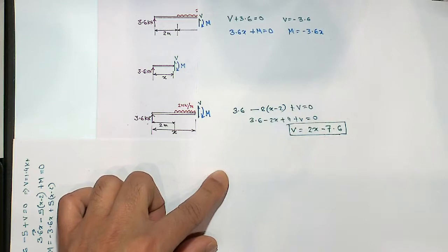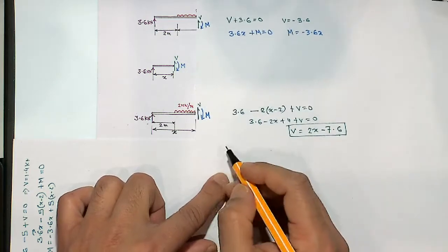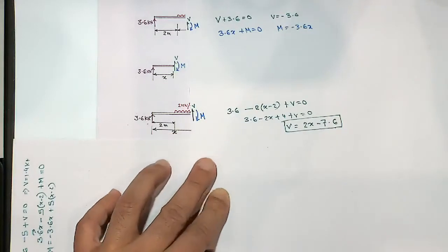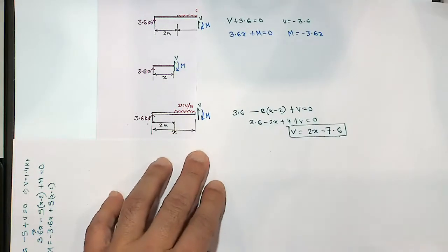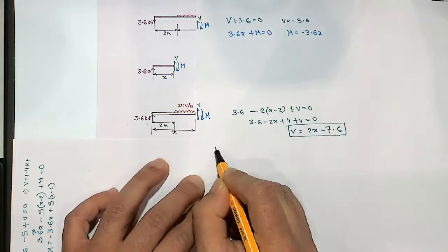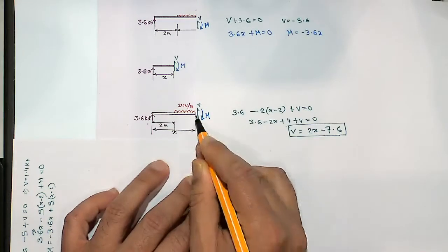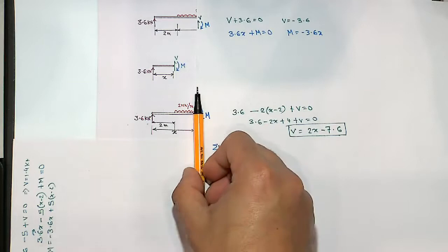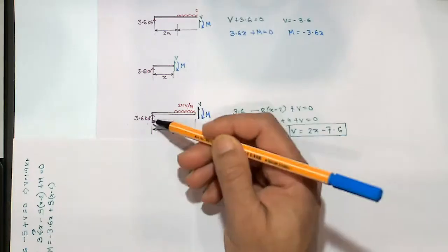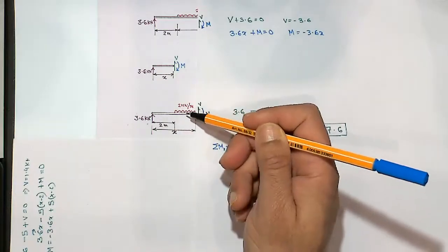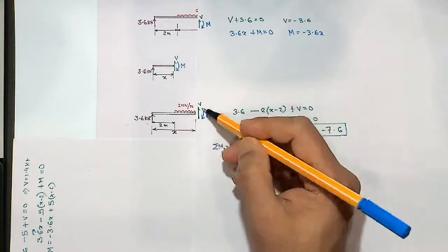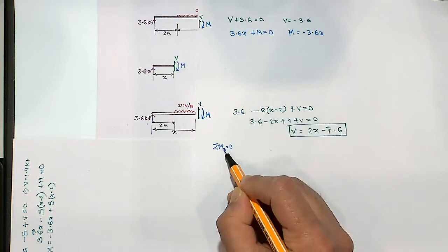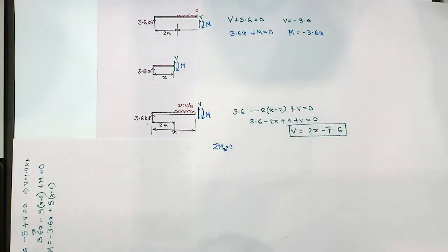What about bending moment? Now bending moment, as before, we will calculate load by load. While calculating bending moment, taking a moment equilibrium, we will calculate. So I'll take a moment equilibrium about this point, about point x. I'll say 0. What are the forces? Forces are this force, this UDL, this shear force, and a moment acting inside the cross section.